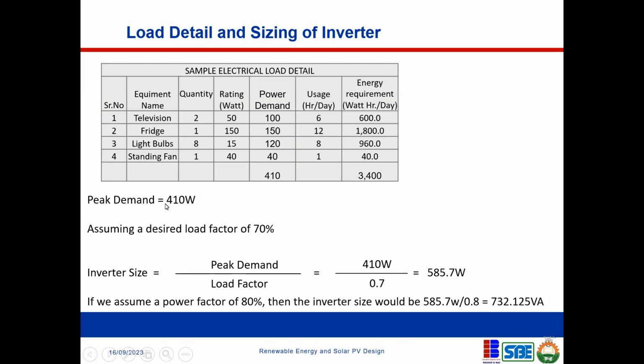So now we want to size an inverter for this client. It is possible that you can look at this and say, okay, the client needs 410 watts, let me go to the market and perhaps look for a 400 watts inverter. Now, some inverters are rated in watts, some are rated in kVA, right? So we need to also be careful when we're looking at the units. Kilowatt or watt is not the same thing as kVA, and the difference is power factor. We are going to see how to use that when calculating the size of the inverter.